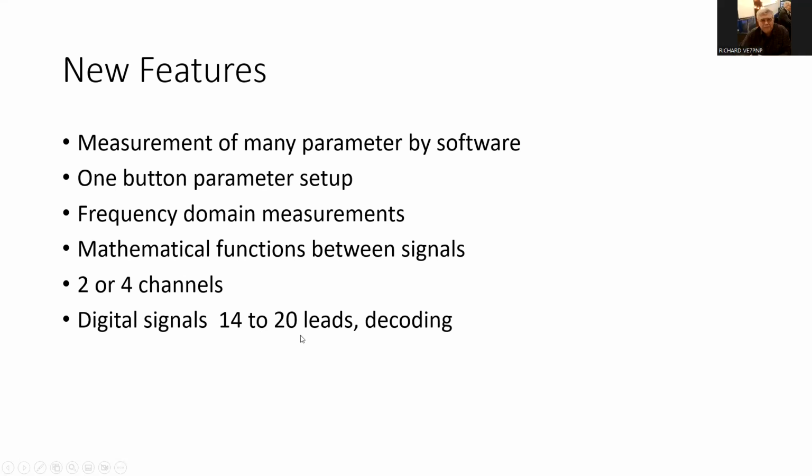A question, Roy. Yes. What you mentioned earlier, the bandwidth, 500 megahertz and all that up. You're talking digital scopes now, not analog scopes. Yeah, I'm talking mainly digital ones because these are the ones that are readily available now. They're basically the only ones. It's very hard to find an analog scope. In fact, it may be impossible to get one that high frequency. They might go to 20 megahertz or something. That's about it. And all the rest are digital. They're sampling scopes, as they call them.